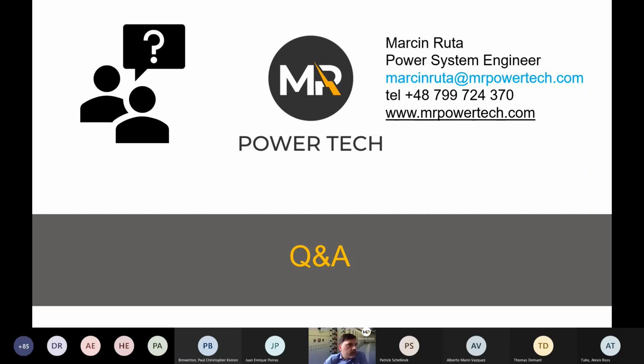And what about Europe? It's a long question. Is 89/391/EEC the only regulation given? Now we have EN 50110, which covers the safe operation of electrical installations and provides you information about arc flash. That comes at a very generic level about work safety. Is there anything more concrete or detailed when it comes to regulation? It's clear that there is no European counterpart for IEEE 1584, but does Europe have clear regulation for arc flash incident and arc flash energy levels?